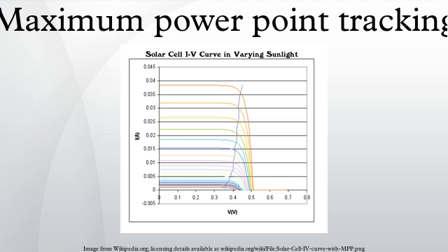It can perform maximum power point tracking under rapidly varying irradiation conditions with higher accuracy than the perturb and observe method. However, the incremental conductance method can produce oscillations and can perform erratically under rapidly changing atmospheric conditions. The computational time is increased due to slowing down of the sampling frequency resulting from the higher complexity of the algorithm compared to the P&O method.